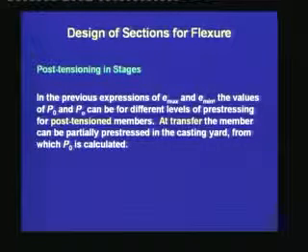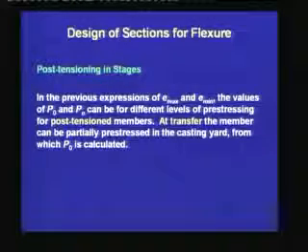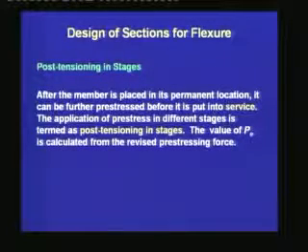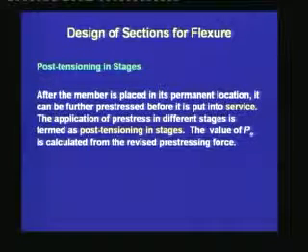At transfer, the member can be partially pre-stressed in the casting yard, from which P0 is calculated. After the member is placed in its permanent location, it can be further pre-stressed before it is put into service. The application of pre-stress in different stages is termed as post-tensioning in stages. The value of PE is calculated from the revised pre-stressing force.